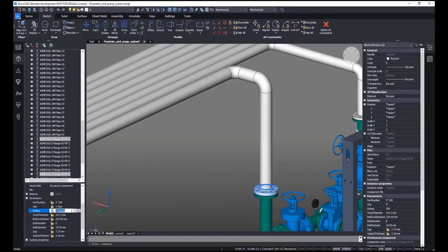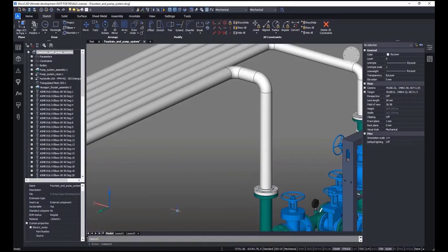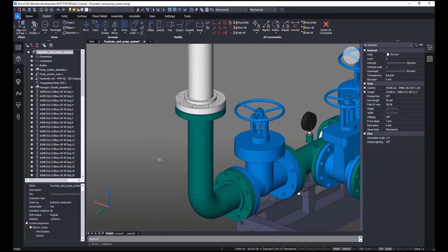But flanges should also be connected with bolts or studs. In version 22, we implemented a new option in BM Connect to automatically insert studs and nuts which connect a couple of flanges. The user can configure which particular types of standard fastener should be used for a bolting assembly. It is also possible to insert a particular gasket between flanges. The generated bolting assembly is fully parametric.